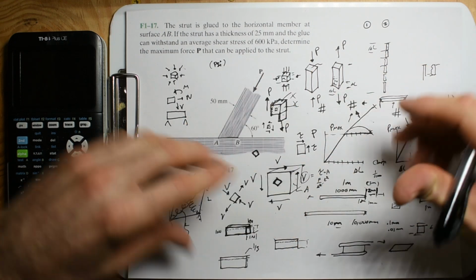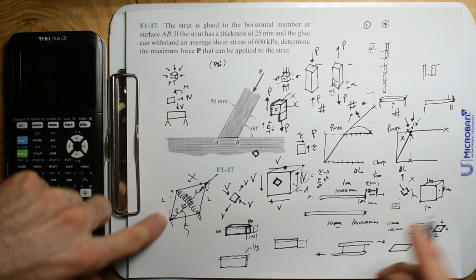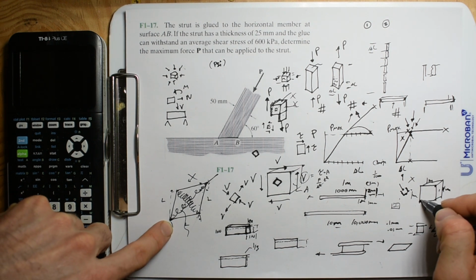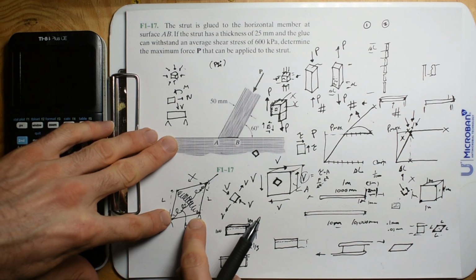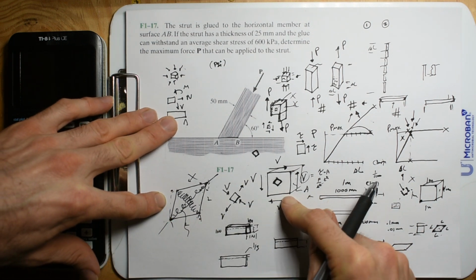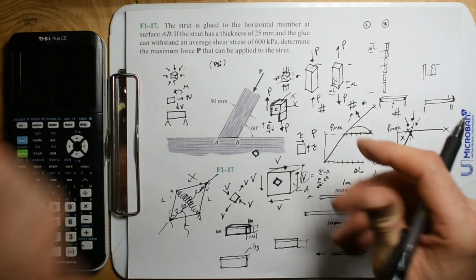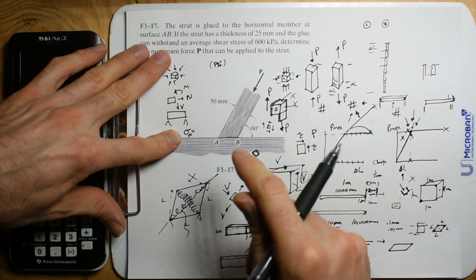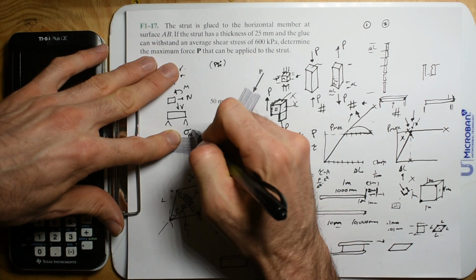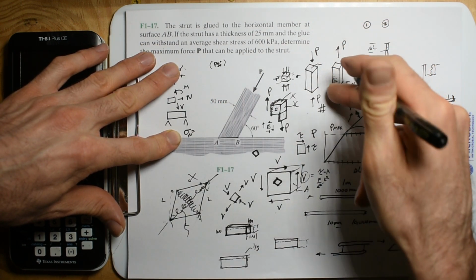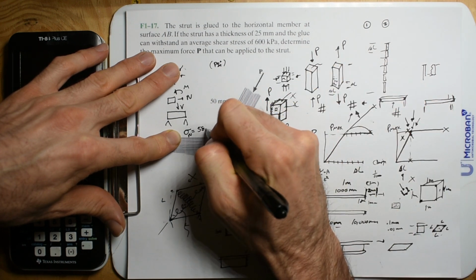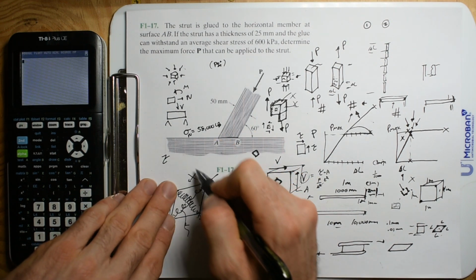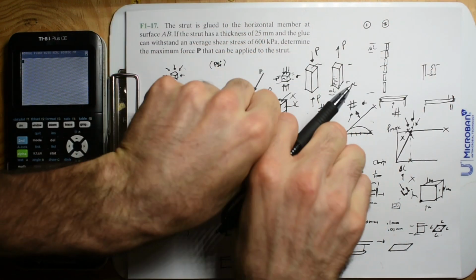We're going to put those shear forces on it, and we're going to get it to look like this. This is one of the most important fundamental aspects of material mechanics, because this is how you relate shear to your normal stresses. The take-home point is, let's say your normal stress for axial tension in a steel rod is 58,000 pounds. Now the question is, what is your shear stress for steel? Like, if I shear it sideways, take a bolt, do that.